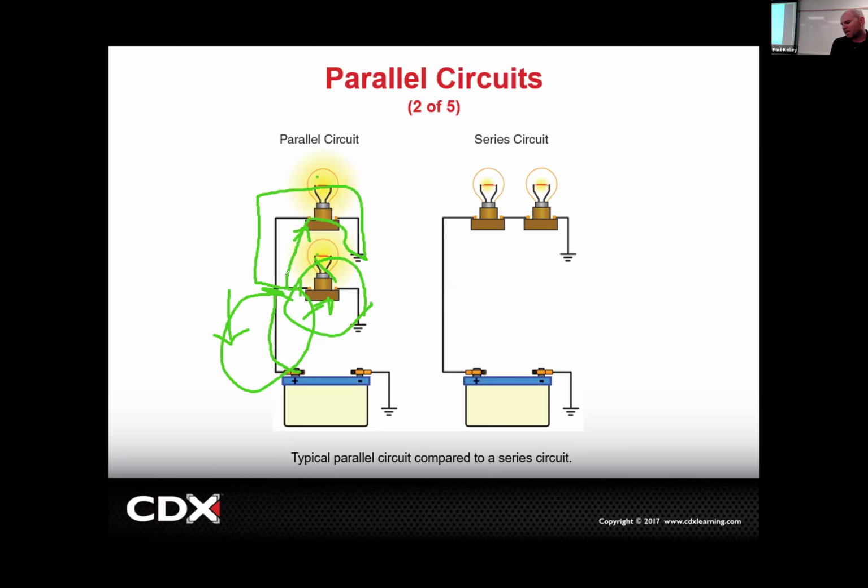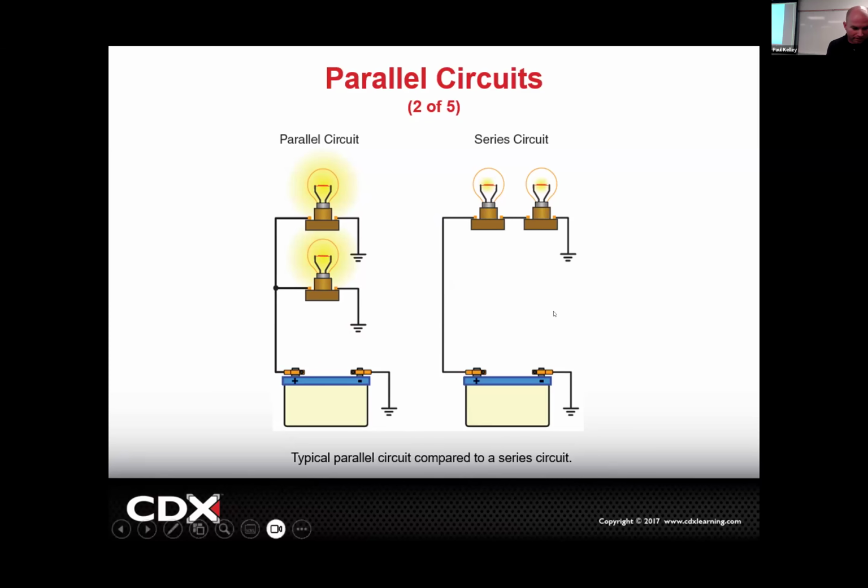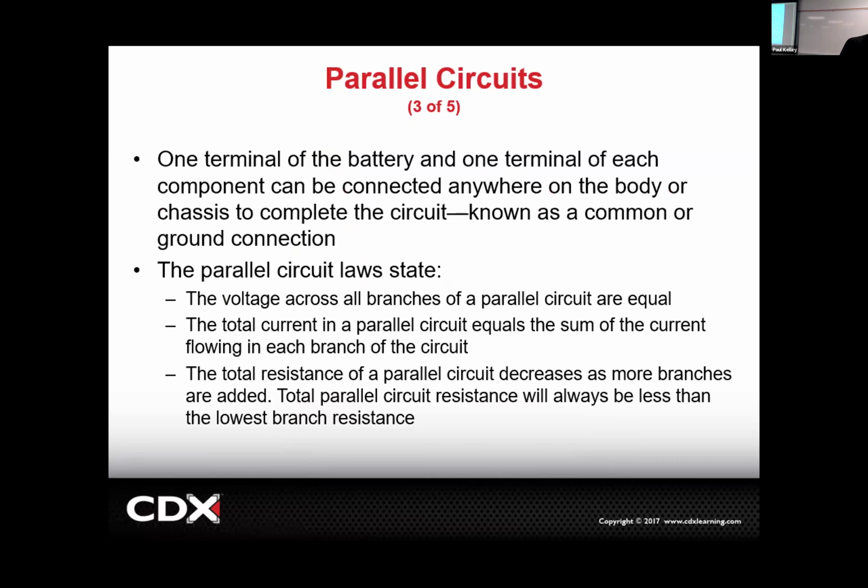On the ASE, there's just basic questions like, if both of these bulbs are out, technician A will say that it's that ground. If you look at that diagram, that ground being bad wouldn't affect the other bulb, and both bulbs are out, so that technician is a no. Make sense? It's actually really simple if you're following what I'm saying. Cool, so that's the main lesson on how we practically diagnose a parallel circuit. Now, of course, to be thorough, we're going to have to throw a little math in there. But again, there's a few laws you must know as well.